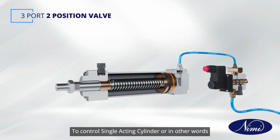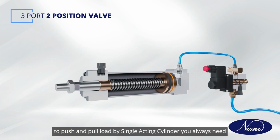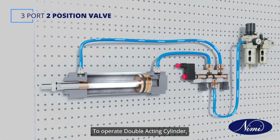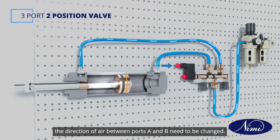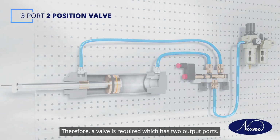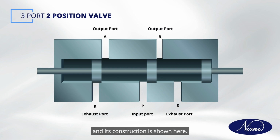To control a single-acting cylinder, or in other words, to push and pull load by a single-acting cylinder, you always need a 3-port 2-position direction control valve as the main control element. To operate a double-acting cylinder, the direction of air between ports A and B needs to be changed. Therefore, a valve is required which has two output ports. A 5-port 2-position valve has two output ports and its construction is shown here.